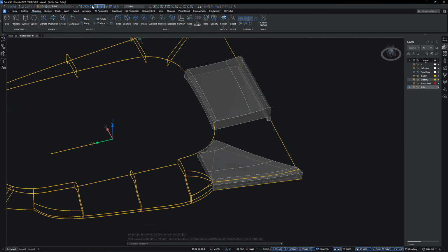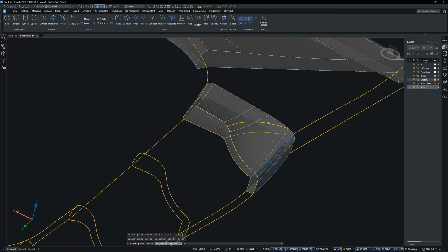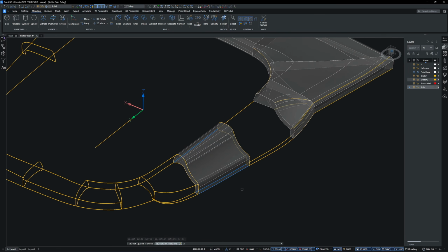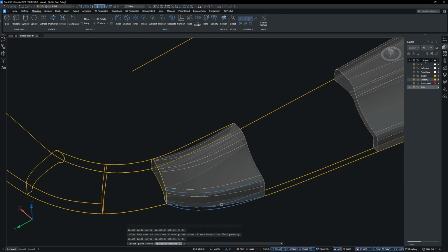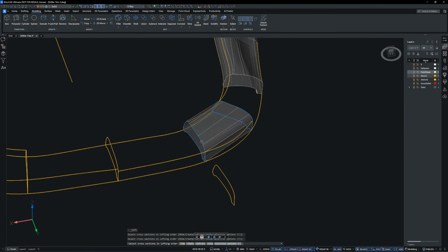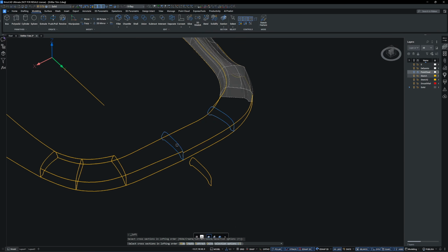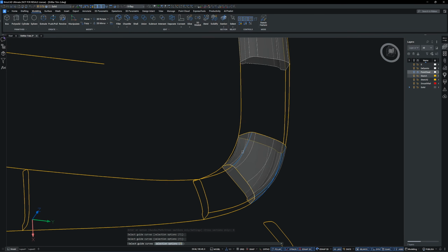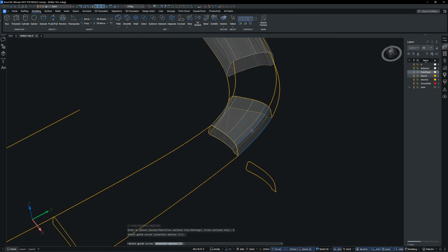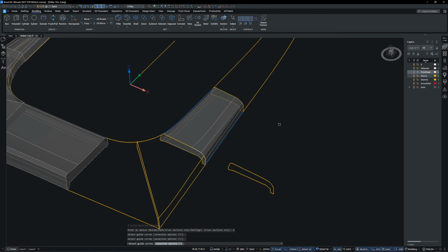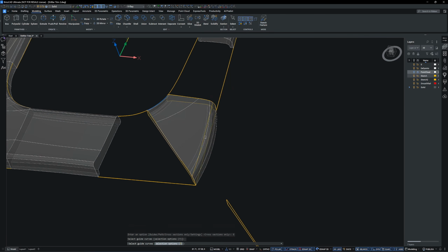Now that all the 2D and 3D sketches are complete, I will begin executing the loft command. Each loft segment is created as a separate entity. If one of them doesn't come out correctly, you can delete it, adjust the sketches, and run the loft command again. In the full tutorial, I placed more cross-sectional sketches, especially along the corners. I add 2 extra sketches for each corner to capture the geometry more accurately.